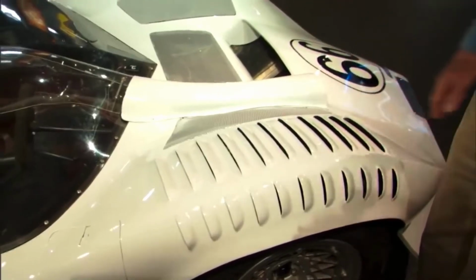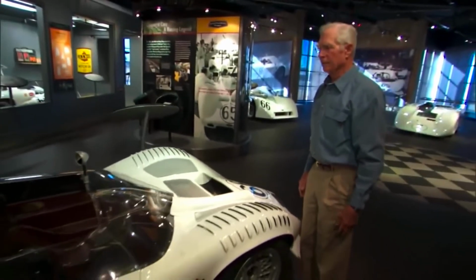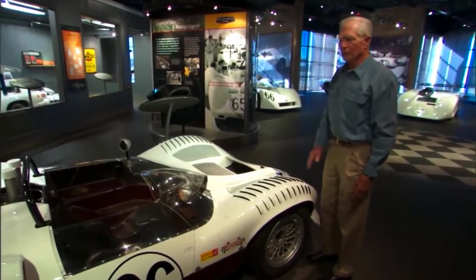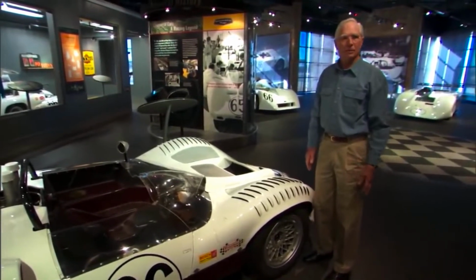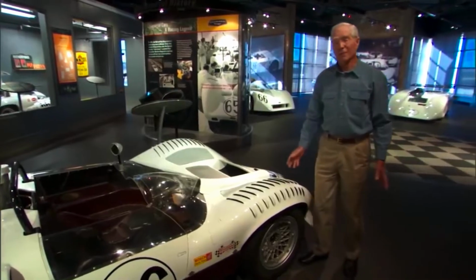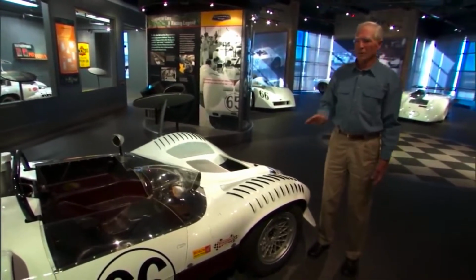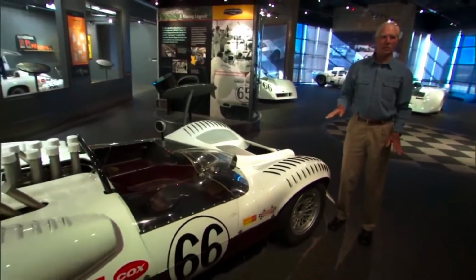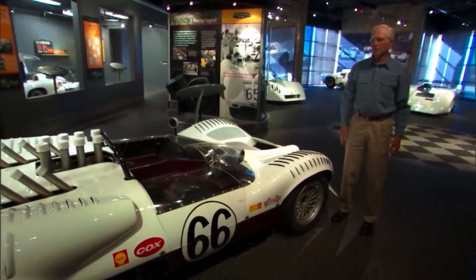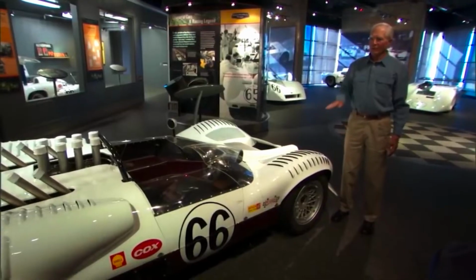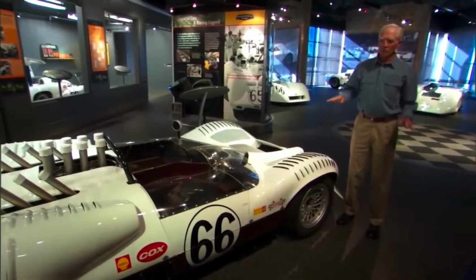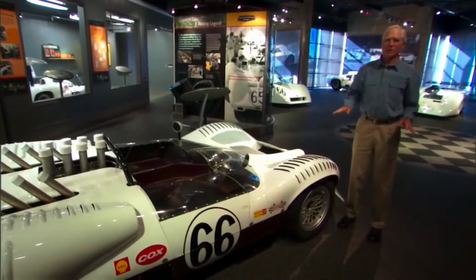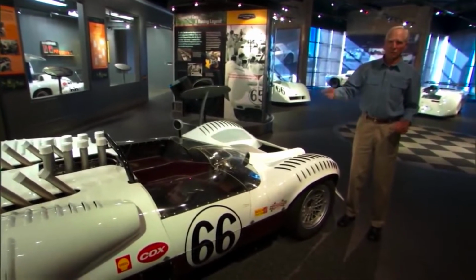All that produced a negative force on the car, which allowed it to grip the road better, and the car went faster and faster and faster. Now, when I say faster, I mean faster around the racetrack. We put a lot of drag on this car. It got slower on the straightaway, and so our next step was to build a car that had a lot of downforce on it, but didn't have the drag on the straightaway, and that's where we went from here.